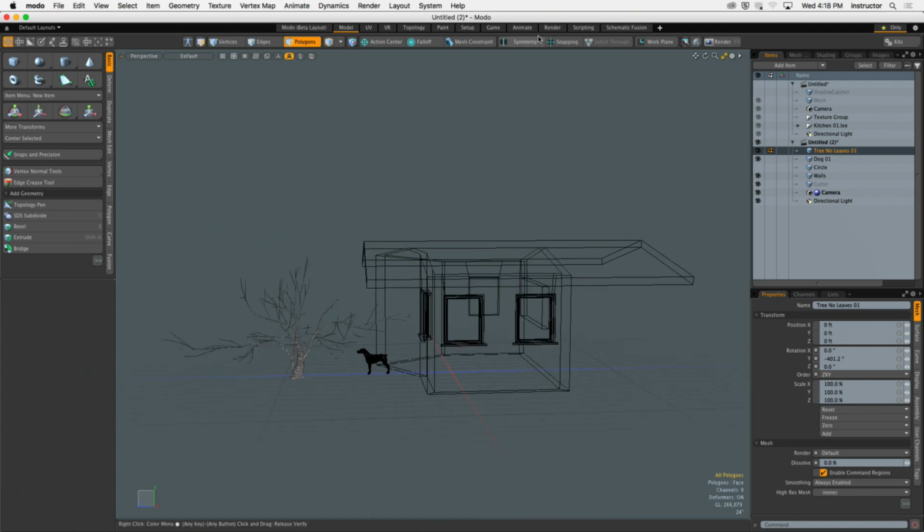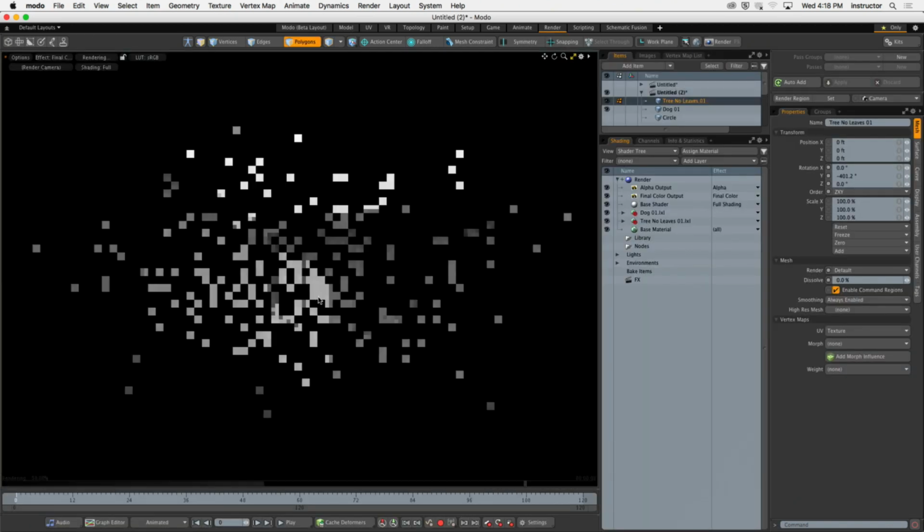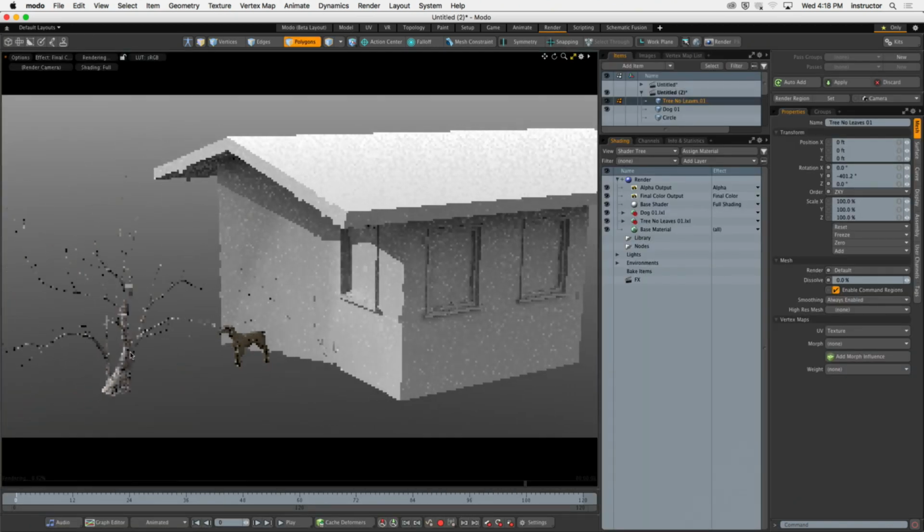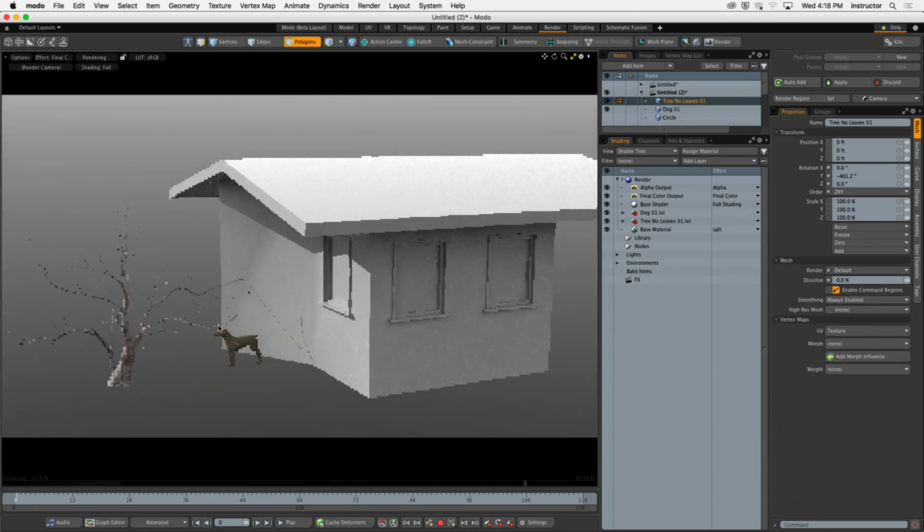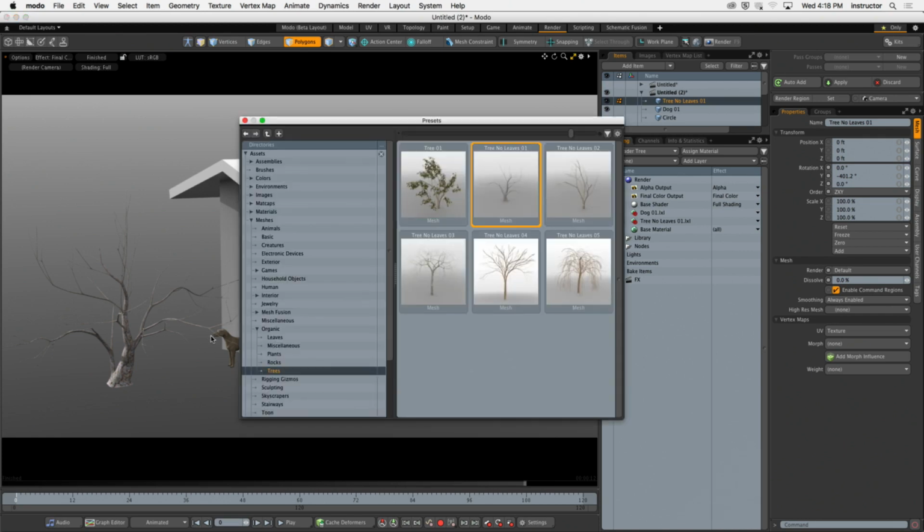But adding these simple little things in here go a long, long way, including the dog and my stumpy-looking tree, to help add some extra details that bring our house into reality. It brings it to life a little bit. So use the tree presets, the bush presets, some of the rocks. Shoot, you can even put a dog in there if you'd like. I don't care. Have fun with it. So you hit the F6 key, it opens your preset library. Okay, F6.